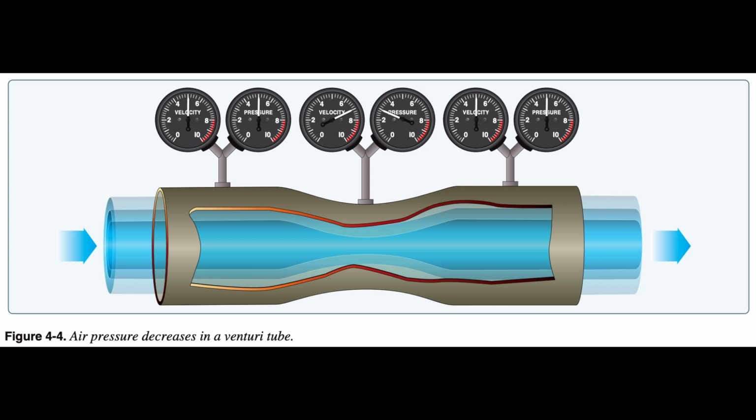A practical application of Bernoulli's principle is the Venturi tube. The Venturi tube has an air inlet that narrows to a throat, constricted point, and an outlet section that increases in diameter toward the rear. The diameter of the outlet is the same as that of the inlet. The mass of air entering the tube must exactly equal the mass exiting the tube.